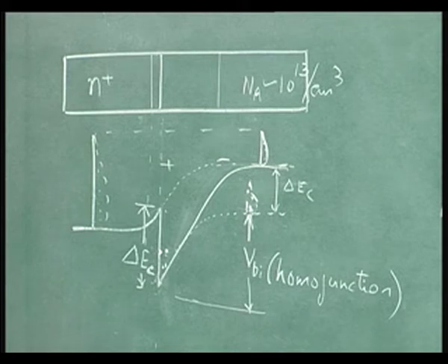The 8500 mobility, 8500 centimeter square per volt second. I must tell the dimensions also, because it is centimeter square per volt second. That is okay for a very pure material. Dopants are small, impurities are absent, but the moment you go to higher doping, like 10 to the power 16, 10 to the power 17, you will have that scattering coming up.